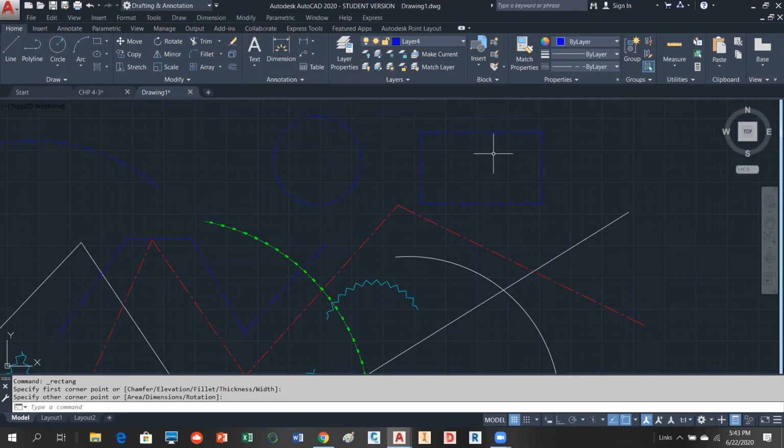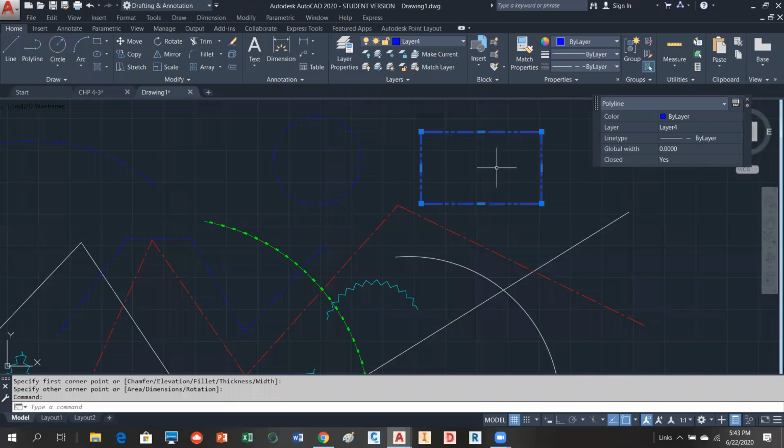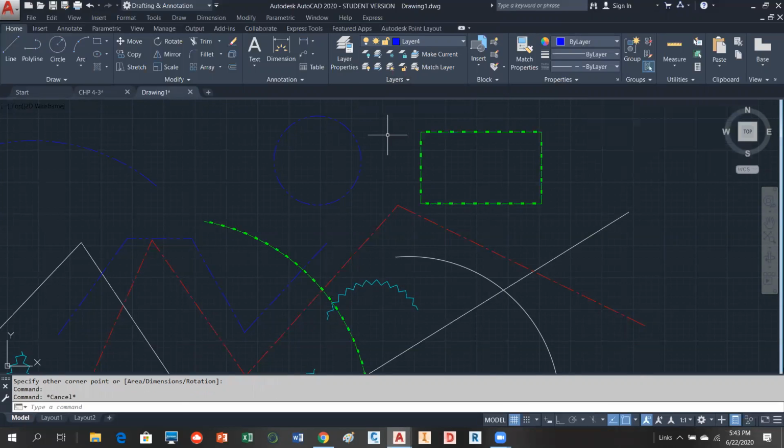So all you have to do is click on the object. It highlights. Up here, it also shows you what layer it's on. If you open this box and say, I really want to move it to layer 2, it moved it. And then when you're done, make sure you hit the escape key to deselect it. So that object is now moved from the layer it was created on to the layer that you wanted it on. Is that working for everybody?